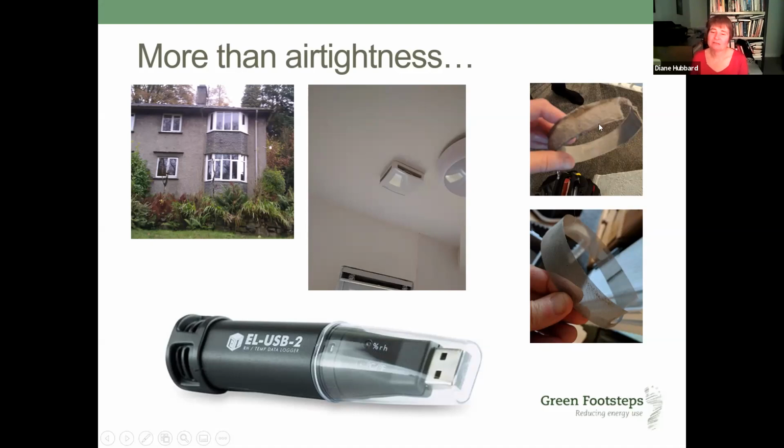It's a really fine filter, and this is a rented property, and they were suffering problems with moisture and condensation, because although the air tightness was addressed, the ventilation hadn't been properly addressed in this instance. And in retrospect, it should have been a more detailed plan.